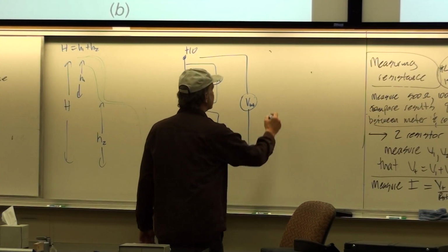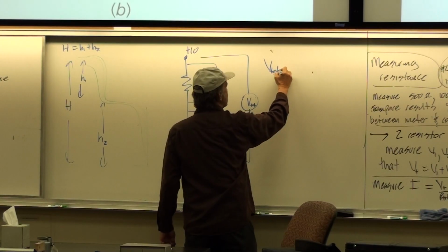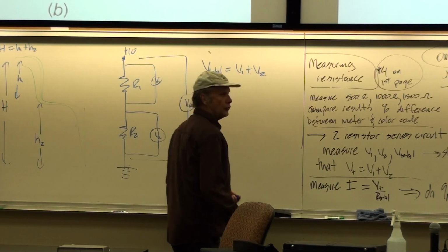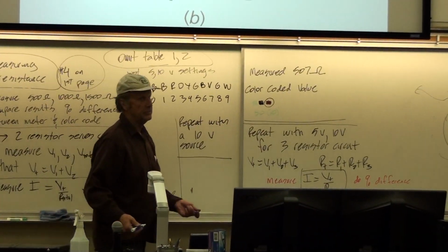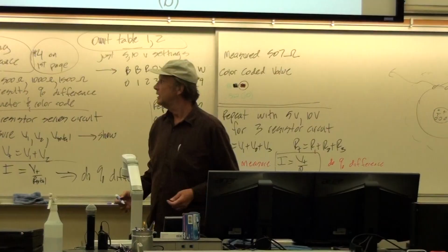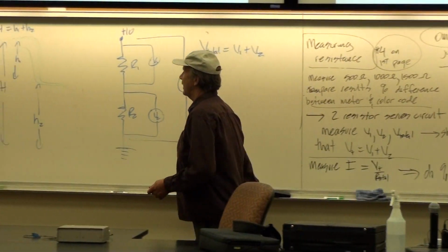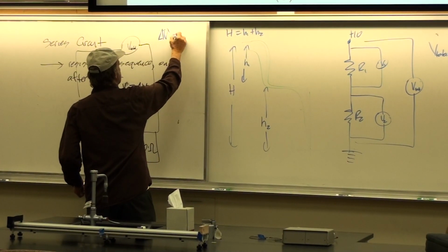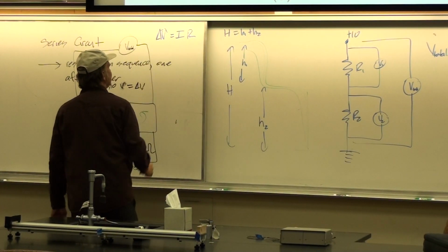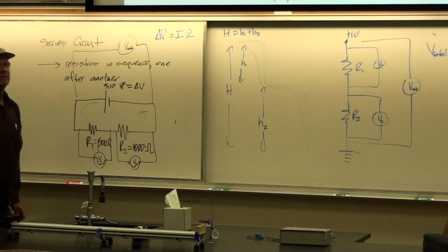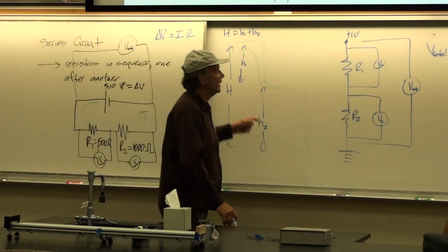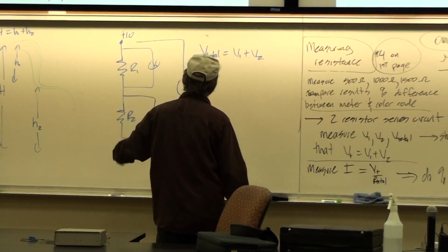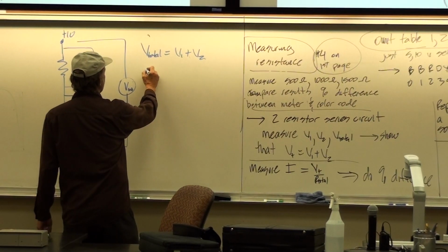And so that's what we get in a series circuit. V total equals V1 plus V2. And if we had 3 resistors, it would be V1 plus V2 plus V3, which we'll get later. So now we use Ohm's law. Ohm's law is kind of like, and I'll derive Ohm's law for you later, but it's kind of like F equals ma. It's our most basic equation for circuits, even though it can be broken down to more elementary things. It's the easiest way to describe everything.